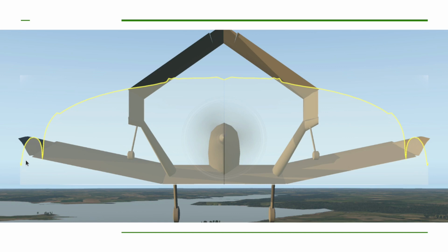But if the load is pretty small here and then increases fairly rapidly toward the middle, that means we can make the spar a little bit lighter because the load is in closer to the middle. And we want to make our spar as light as possible. So we really want specifics on what this load distribution is, so we can make that spar match exactly what the distribution is without having any extra material.